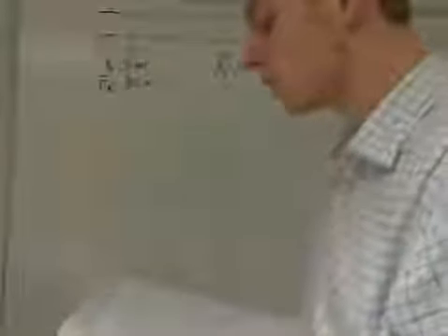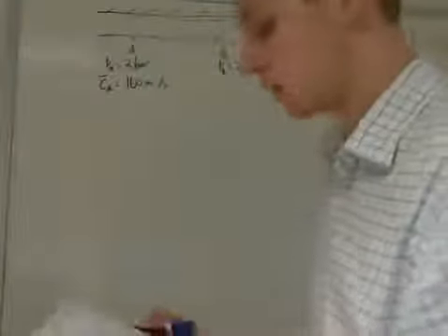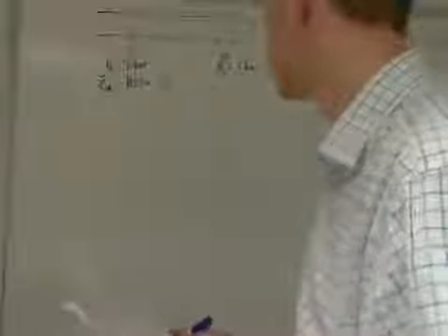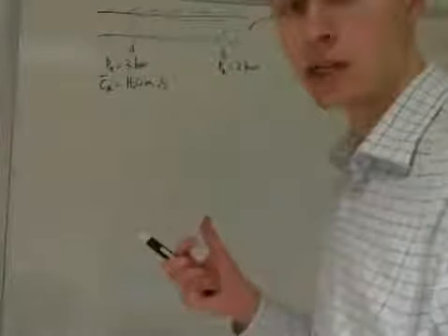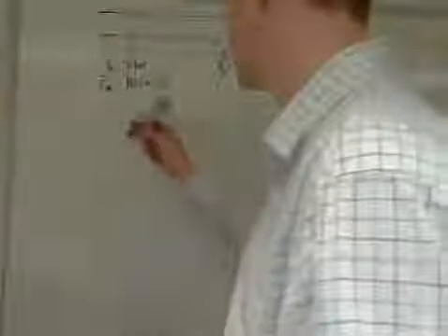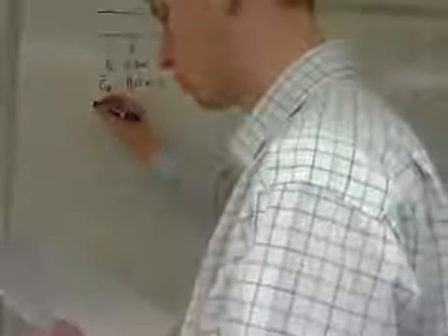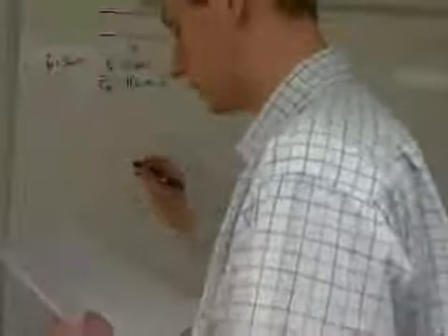So we know the working fluid is air, so we're going to treat it as an ideal gas. And there are two principles we can apply in order to solve this problem. The first is the ideal gas equation, the second is mass continuity. So all the mass flowing at point A has to, by steady state, flow through point B, or the same amount of mass has to flow through both places. So the temperature at A is also 300 Kelvin.